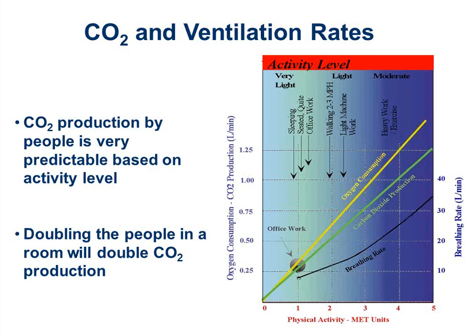Jeff asks, what about CO2 equalizing from floor to ceiling? The answer to that is yes, Jeff. It does equalize. Now, obviously, if you're in a tall space with 30-foot ceilings and everybody's down at the 5-foot level breathing, there's going to be more CO2 there than there is at the ceiling.